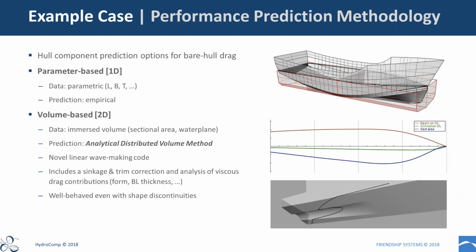However, that value can also be at a point where the draft is not maximum or the beam is not maximum. You have variations in shape, particularly for hulls of this type, so a shape function that you're trying to use to describe the central girth of the ship sometimes overly constrains what you actually want in terms of an outcome.